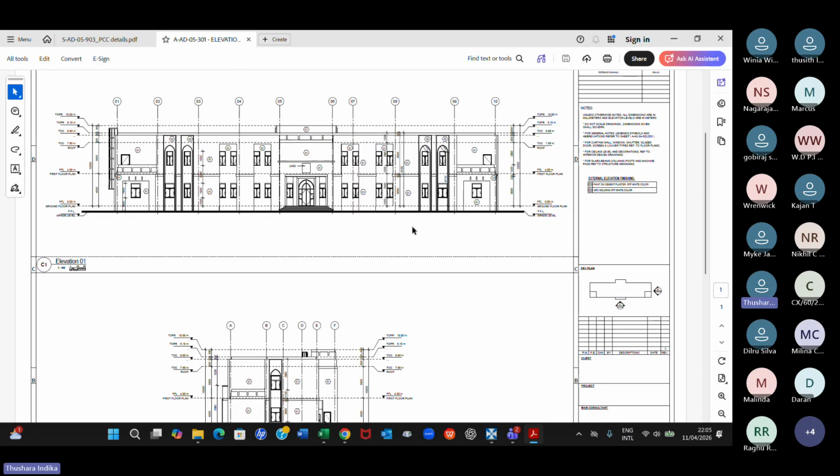It's about applying quantity surveying principles to the quantities. Now you can see here you have level 1, level 2. This is a two-story building, and sometimes, especially in Sri Lanka, the measurement rule, the standard method of measurement SLS 573 we use here, requires your quantities to be presented level-wise.